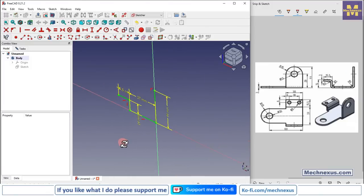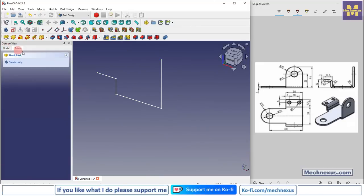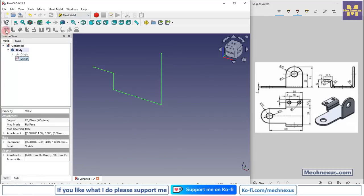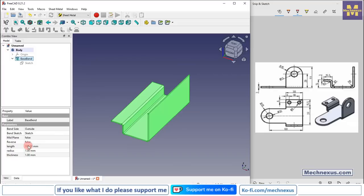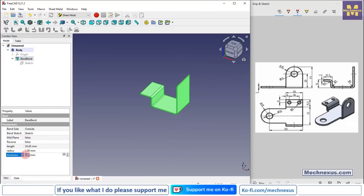So this is our front profile, and we will come out of the sketch, and here we will switch to the Sheet Metal Workbench. Go to the model tab, select the sketch, and create a bend, and now we will provide the length. Length is of 30 mm, and thickness is of 3 mm.